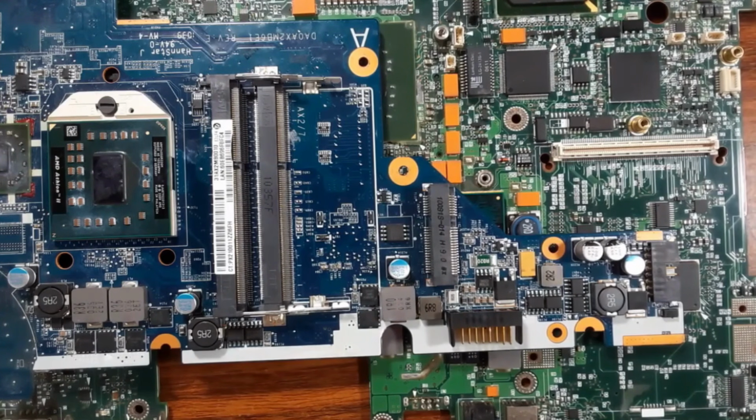The next fault is the dead motherboard. If you have a dead motherboard, when you press the power switch or the power button, you don't get any response, no light, no indication in the computer, the probable cause of failure is the BIOS. You should reprogram your BIOS. Of course, you should first check your adapter. If you have a laptop, you should always check your adapter, especially if you don't install the battery. Okay? When you have a good adapter or a good battery and the computer won't start up, the problem is in the BIOS. You should reprogram it.